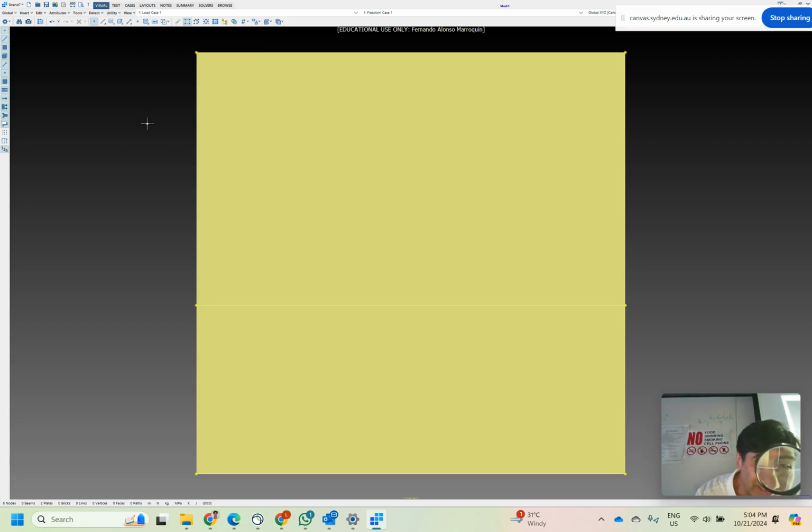I want to select not the node, but the element. So I need to click here, that is select, plate select, and then I'm going to select by region here. And then I think one was selected. If you are not sure, here you see two plates and all have been selected. Okay, no, this is not correct. Probably I need to unselect this one because I selected before.